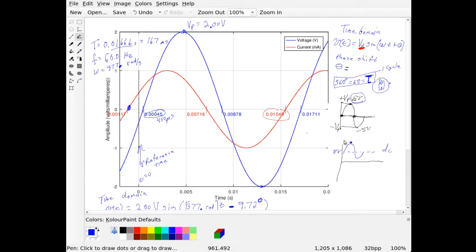So the peak value now, when the sine wave is at peak and it's 5 volts, you have 8 plus 5, so it would be peaking out at 13 volts, and then the minimum here would be positive 3 volts. Okay, so what happens there is you have a DC voltage and an AC voltage, so the DC voltage is basically riding on top of that.